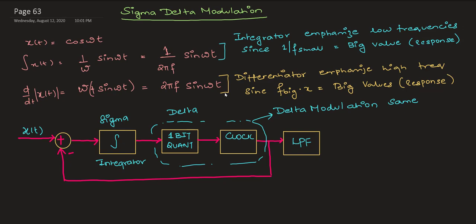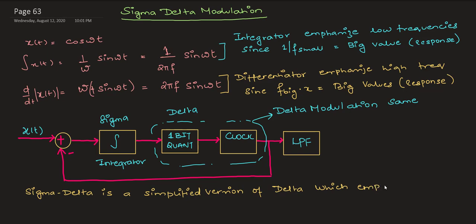So this is sigma delta modulation. I think today's class covers most of it, and whatever we have seen is important. We have seen everything related to oversampling and A to D converters. When I talk about oversampling, you have a high sampling rate and a low resolution quantizer. A high sampling rate can be achieved just by increasing your fs, or the Nyquist rate, way above 2 f max. So we are increasing the sampling rate, which means your samples are closely placed, and for that you need to adjust your quantizer, and those are the designs we have seen today.